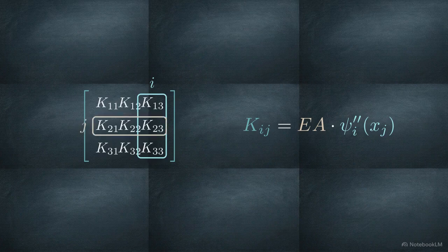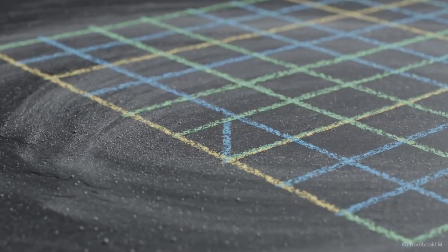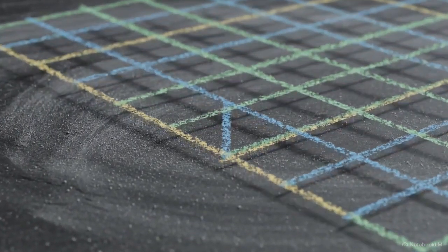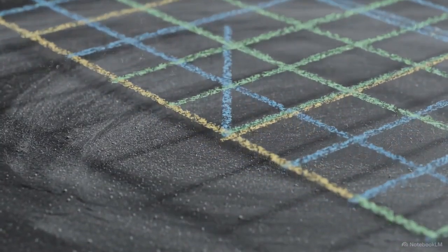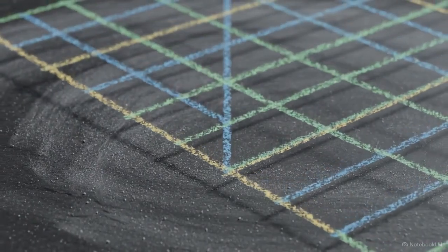This formulation reveals a critical trait. Unlike standard finite element matrices, mirroring cells across the diagonal are not equal. The resulting stiffness matrix is generally asymmetric. The resulting asymmetry stems from the specific points we've sampled and the inherently non-symmetrical physical conditions at the bar's fixed and free ends. We began with a continuous physical structure governed by an equation with infinite possible deformations and forced it into a solvable, programmable grid.